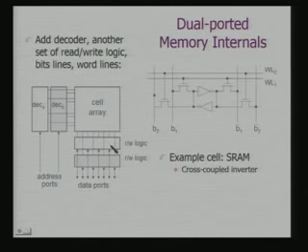This is where the read-write logic will come in, and in this case the picture is something like this. You have the same inverters, and now in this case say 2 bit lines. These are bit and bit bar. So, you can have simultaneous access, because I can sense B2 and B2 bar and read the data.